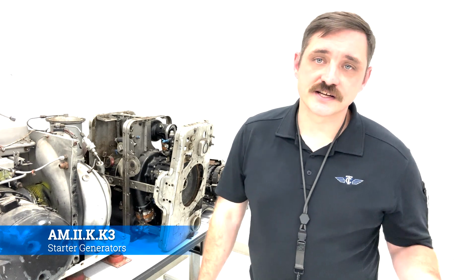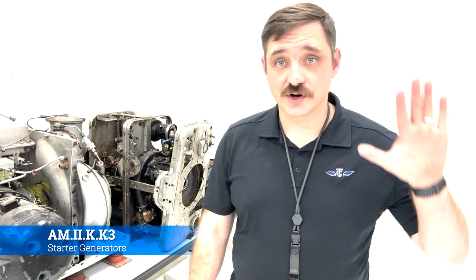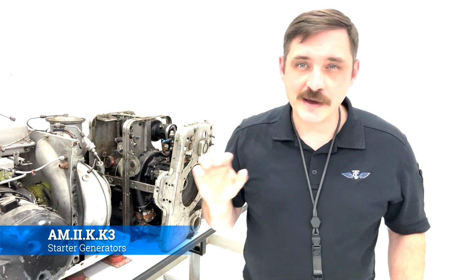All right, it doesn't make a lot of sense for an aircraft to have a starter, which is effectively a DC motor, and then a generator, which just generates DC power. It would make a lot of sense if you could put those together and make one unit out of two different units. You would save weight, you'd save the complexity of it all, and you would be able to do a lot more with just one thing. Therein lies the beauty and the brilliance of a starter generator.